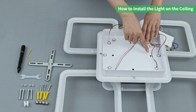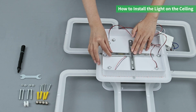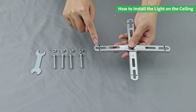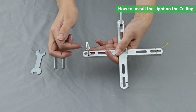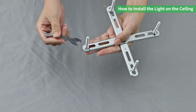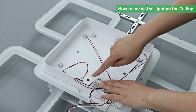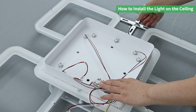First, ensure that the holes on the outer ring of the cross bracket are precisely aligned with the 4 holes on the light base. Use a marker to accurately mark the corresponding points for the light base holes on the cross bracket. At each marked point, insert a screw and secure it with a nut. Use a wrench to tighten the nuts to prevent screws from shifting, ensuring a perfect fit with the lamp base. You can test the cross bracket with screws tightened to see if it perfectly aligns with the 4 holes. If it doesn't align perfectly, adjust it until it matches perfectly.